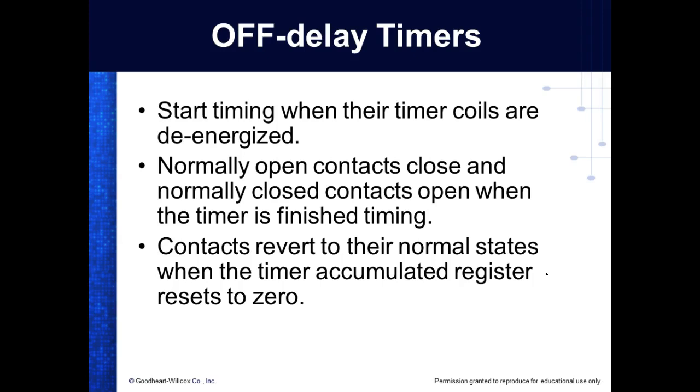So if I've got an internal relay, or if I'm using a normally open contact from a coil, when that coil is energized, that contact is closed. And when that coil is de-energized, that contact is open. If it's inside there, right? You understand. But when I'm coming from an input, from an actual physical input device, that's where you're concerned with the what? Examine open and examine closed.